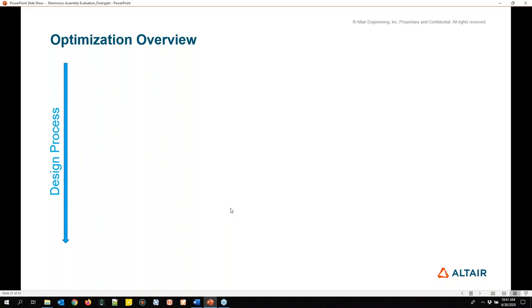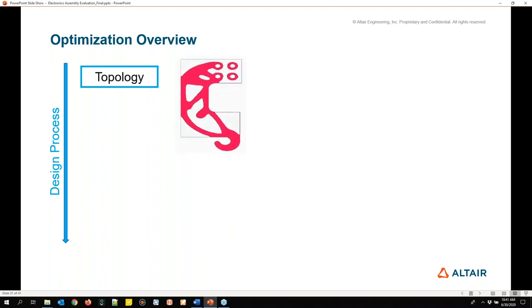To preface this, I want to talk about the different generative design tools and optimization capabilities we have within the same platform. One such tool is topology optimization. Topology optimization is basically material removal and redistribution. The topology optimization tool uses the solver in the background to retain material where the majority of the strain energy is, so that it's a load path dependent design generation. So basically, you're going to get a design generation that lies along the load path of the applied load.